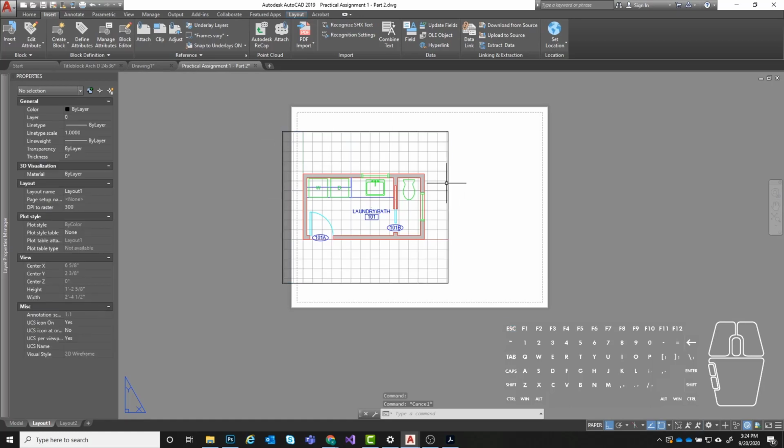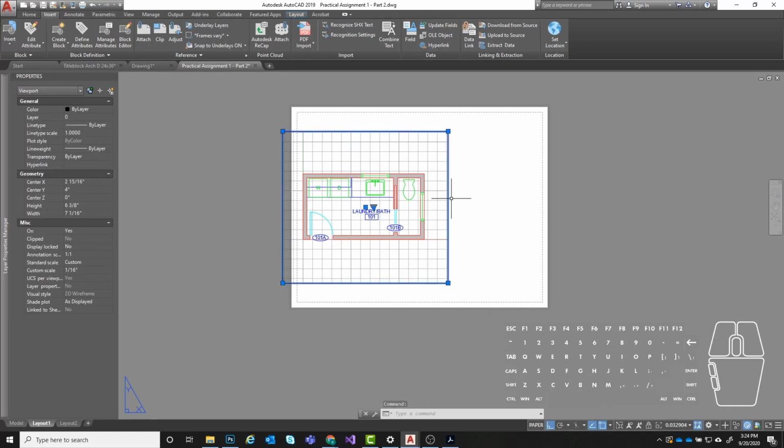So to set the drawing scale correctly, what you have to do is click on your viewport while you are in the paper space mode. Click on your viewport, and then down here at the bottom right, you're going to see probably what I'm seeing here, just a bunch of decimal numbers. Okay, now when you hover over it, it says this lets you scale the selected viewport.